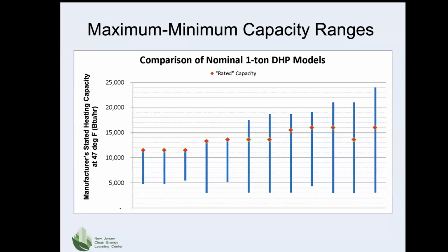So the one to the right would be the one, if you wanted, it can certainly operate efficiently as the others within its mid-range, but they're more capable of performing efficiently over this wider range because of increased surface area, the ability to vary the flow of the refrigerant, as well as speed down the electric motors for the compressor and the fans.